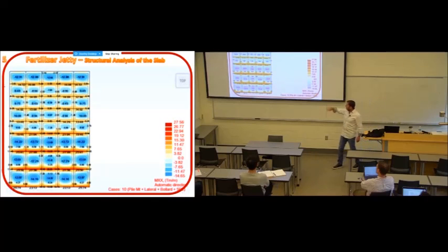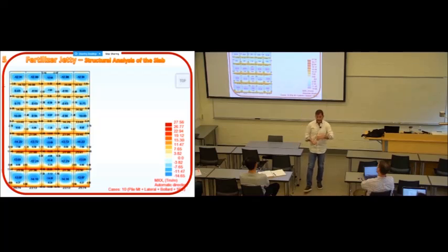You see in red the negative moment on top of the beams, and in blue the positive moment in the middle of the slab. You have to satisfy this. This is how you determine how much steel you need in the slab, or if it's too much steel, you make it thicker, etc. If the steel is provided by the client and you are the contractor, you make the slab thinner to gain more money.